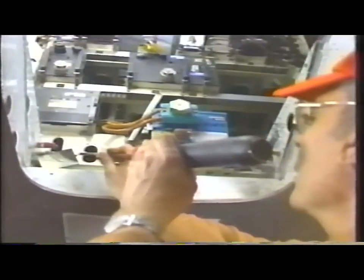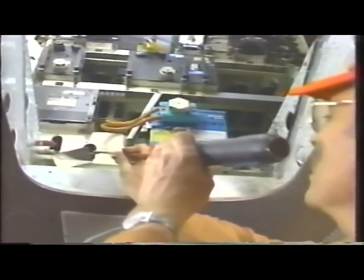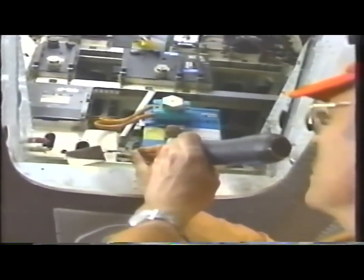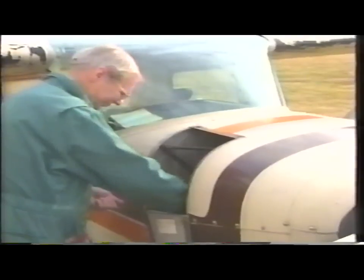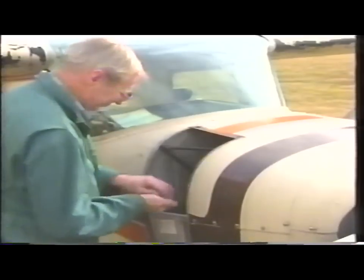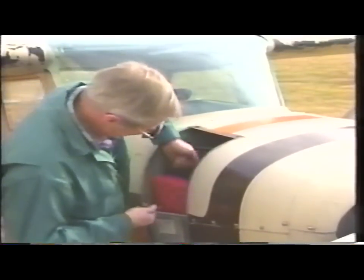Frequent cleaning of the battery compartment and neutralization of the electrolyte will minimize corrosion. Also, you can spray a corrosion preventive compound on surfaces within the compartment to provide extra protection. If there are external battery vent openings in the aircraft skin, they should be included in inspection and maintenance procedures.